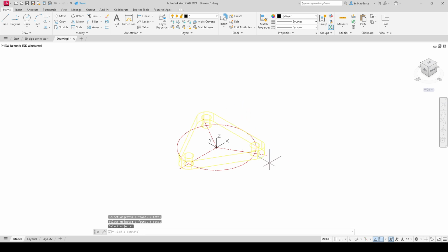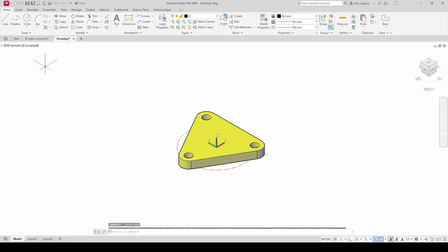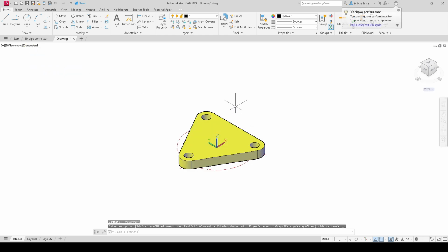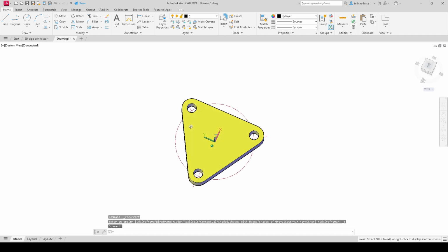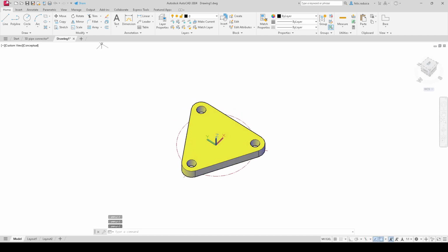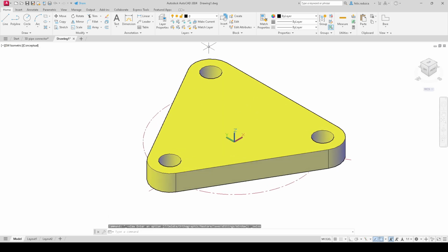And now, as you can see, these look like they have been switched to the outside geometry layer, but actually the operation of extracting the holes happened. So now we can move and see that we have our bolt holes created for us. So set the isometric view here back to the southwest isometric.